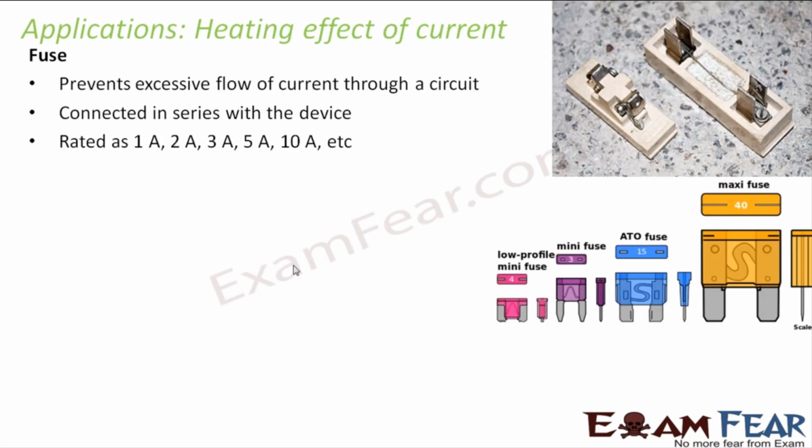Let us look at another important application, that is the electric fuse. You would have seen that there is something called a fuse at your home. What is the purpose of the fuse? It prevents excessive flow of current through the circuit. As I mentioned, sometimes excessive flow of current can damage the different components present in the circuit. So in order to prevent that, a fuse is used. A fuse is connected in series with a device, and if you connect two things in series, the same amount of current will flow through each of them. So if some excessive amount of current I is about to flow through the device, the same current will have to pass through the fuse first.